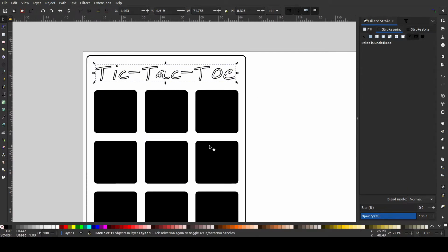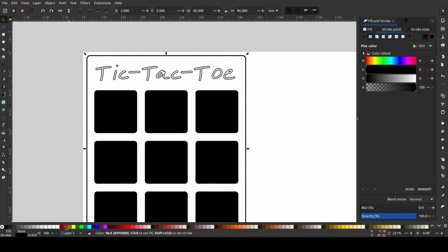And the last thing that we need to do is we need to assign separate colors to the outside path, the lettering itself, and the pockets. Now the Glowforge will allow you to assign different cut functions to different colored lines. That's just how the Glowforge works. And so it doesn't matter what colors you use, just use different colors in order to be able to make separate assignments. So I want this outside path to be a cut path, so I'm just going to choose a random color here. I've chosen red. It doesn't matter what you choose.